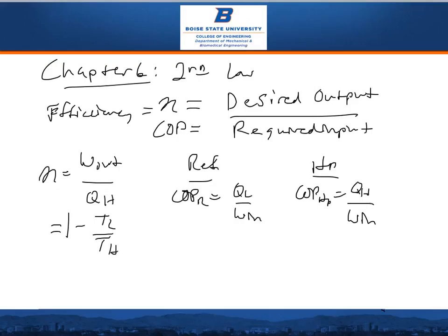For refrigerators, it's 1 over TH over TL minus 1, and 1 over 1 minus TL over TH for heat pumps.